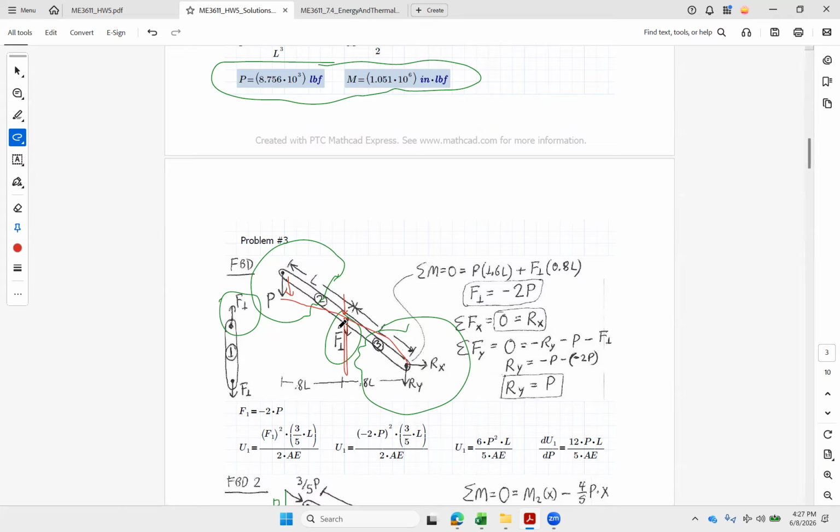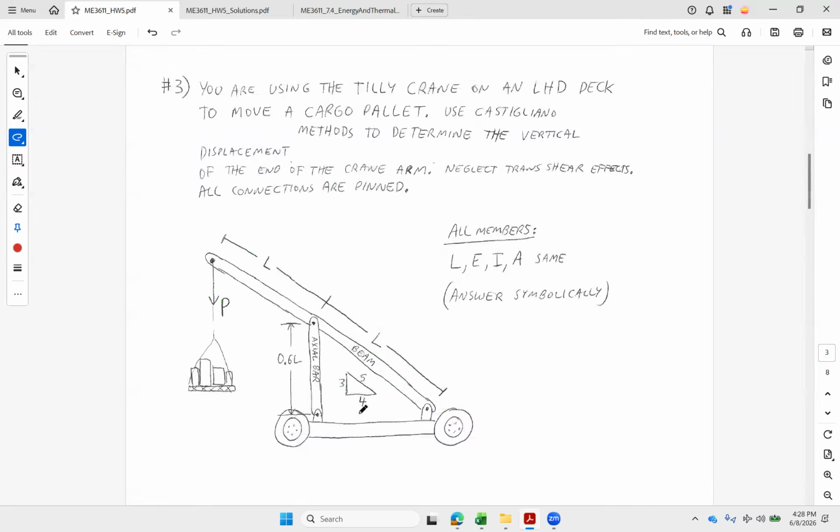And all those movements get combined, and we don't have to think about them. We're trying to calculate how much rotation do I have, plus how much distortion, all that. As long as we did the energy in here, it all counts up and gives us a deflection. So there's our multi-part Castigliano in action. Any questions about that?